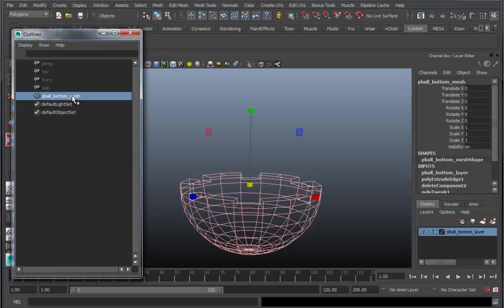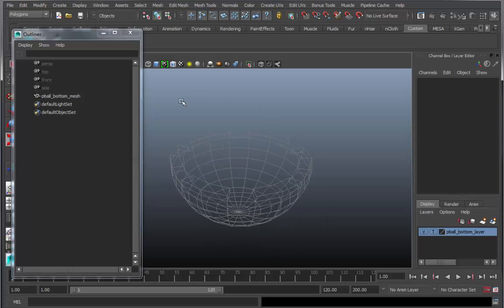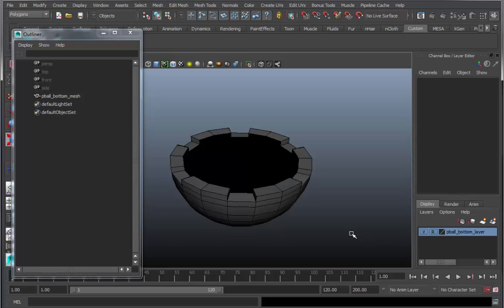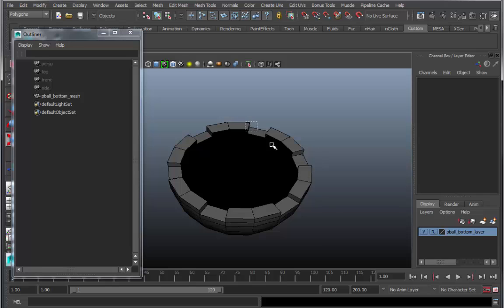It's always going to be selectable here in the outliner. But it allows you, again, to have a very complex scene where this is just one component where you want to see it, but you don't want to be able to select it. And the next option after T, click it one more time with your left mouse button, is something called R. Now this is a little friendlier to me. This is where you can see it in a shaded mode and yet just as unselectable.